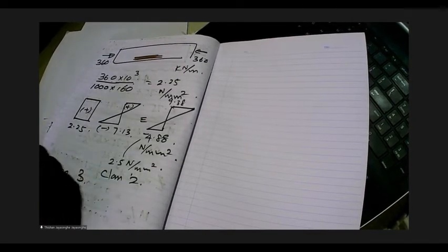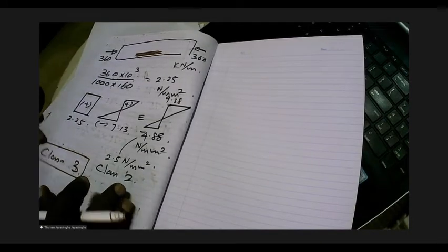On the other hand, what you can do is design it as a class 3 member. So you can see one-way span slabs, we might need some high pre-stress. We cannot just compensate only the dead weight. So when you go for high pre-stress, what is the problem? The slab is cast like this. What will happen? It will lift up.